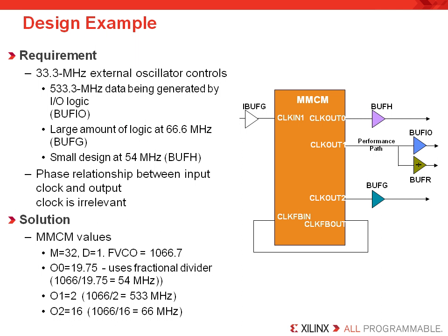This example shows how a single MMCM can be used to generate multiple clocks required by your system. Now recall that the M multiplier and D divisor values are applied at all output ports, which means that the VCO value has to be divided down at each port. Now, the benefit of using the MMCM to build this is that it saves you from purchasing extra clock components and reduces your overall system cost.